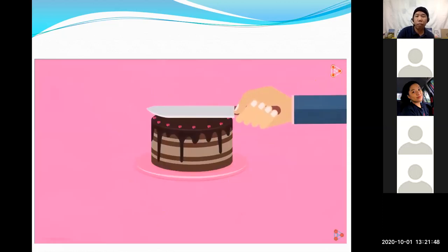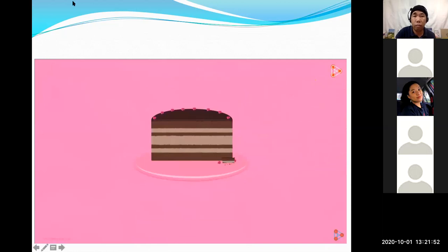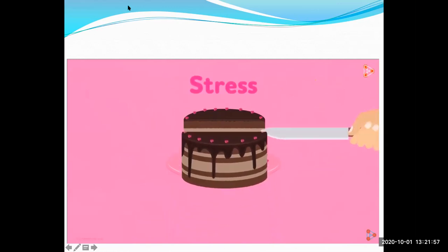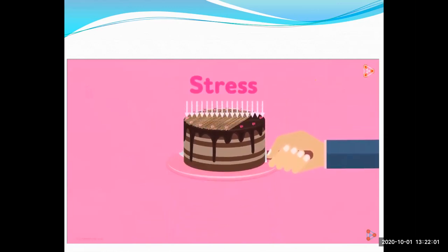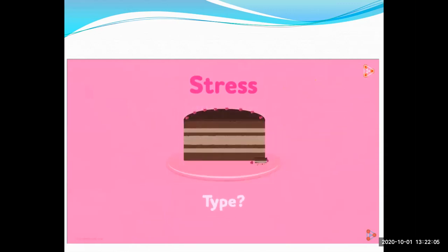What really happens when we cut a cake using a knife? In physics, we could say that the cake experiences stress. Usually when we cut a cake, we hold the knife straight and apply the force perpendicular to the surface area. So can you guess what type of stress this is? It is normal stress, as the force is acting perpendicular to this area.